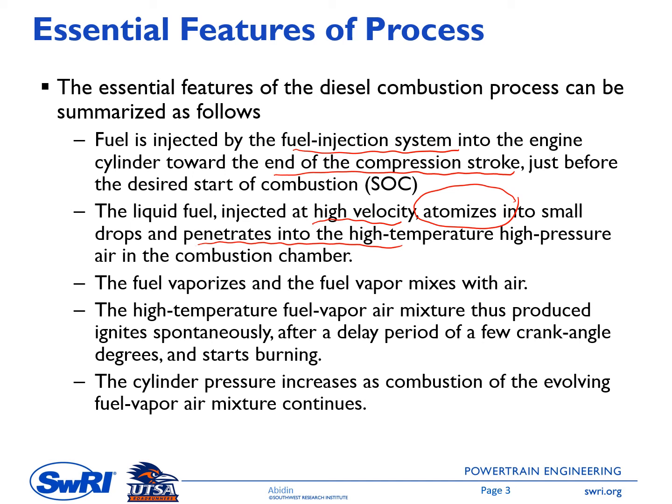So once again, this fuel injection is at the end of the compression stroke. So the mixture inside the cylinder, which consists of air and residual and maybe EGR, are already at high pressure and high temperature. And then because of this high temperature surrounding condition, there will be a heat transfer from the mixture of air and residual into the fuel. So the fuel drop will vaporize and it will form a fuel vapor. So in the end of this step, there will be a mixture of air, fuel vapor, residual, and maybe EGR.